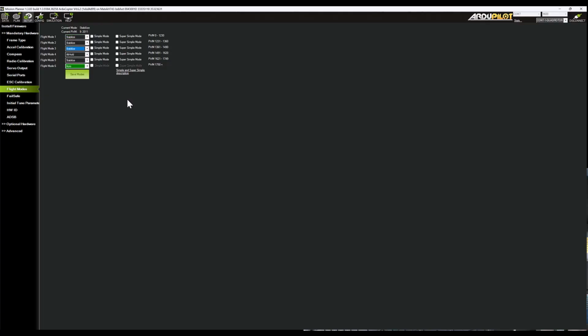So everything works fine. If you have a compass, obviously you can assign additional modes, and for this you need to use a different tumbler or a different set of buttons. On my RadioMaster, I have 6 buttons in a row that I just treat as a single tumbler. You can pick, for example, a mode that returns to base, like RTL, or a mode that just lands your drone, depending on your previous state.